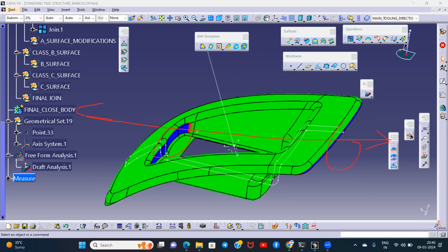So I need to rotate this line by trial and error, either in this direction or this direction. How much angle do we need to rotate? Our formula: if I want this surface to turn green, its value should be 3 degrees. So if I want 3 degrees, the value in brackets is minus 16.54. I'll take a rounded-up value of minus 17. And 3 plus 17 is 20.